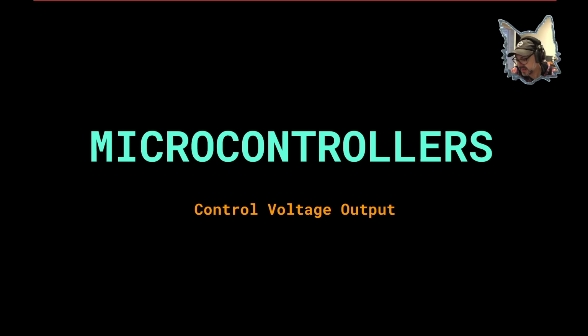I happen to have an MCP4822, which is a 12-bit digital to analog converter. We're going to be making use of that particular digital to analog converter today, and we're going to be using a Blue Pill for this, okay? And the Arduino framework.